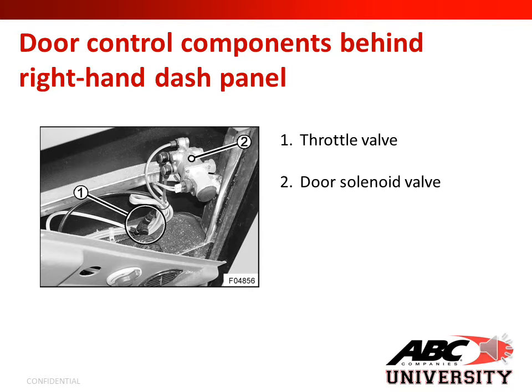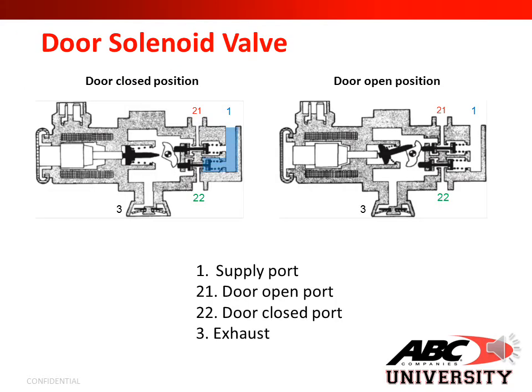Door control components behind the right-hand dash panel. Number 1, you have your throttle valve. Number 2, you have your door solenoid valve. In this slide, we're going to show you an example of how your door solenoid valve operates when opening or closing the door.